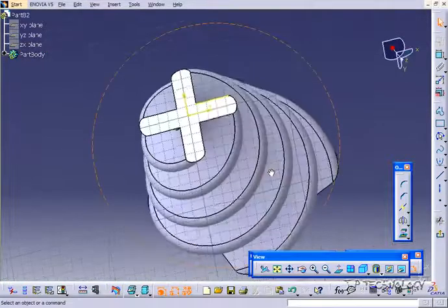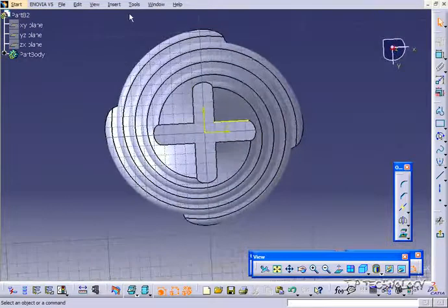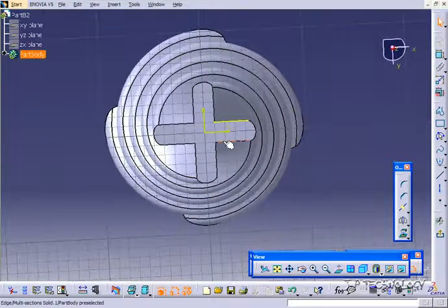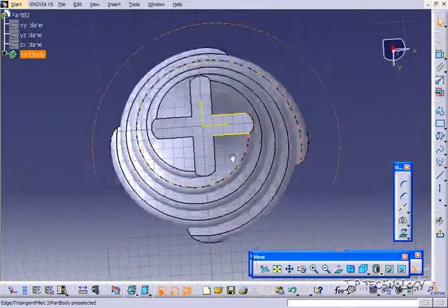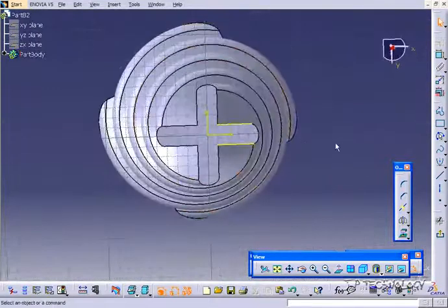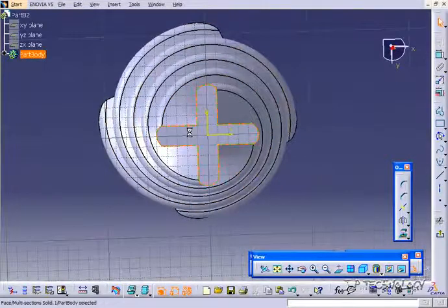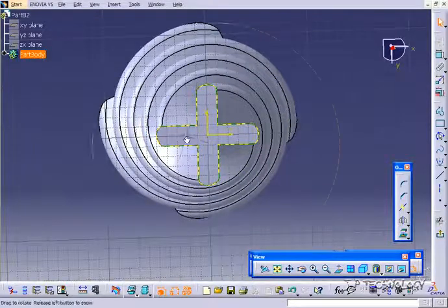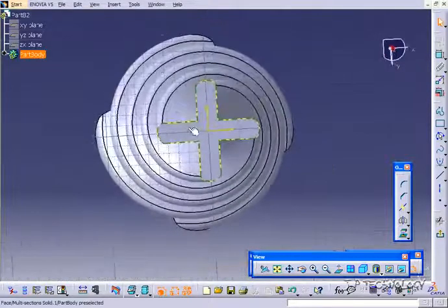Whenever you project them, they're going to be yellow unless you've changed it in your tools and options. Now it can also work the other way. You can click a line and you can click project and it'll be projected. Now you're also able to click on, say, a whole face. So let's click this face, click project, and we projected all the lines touching that face.